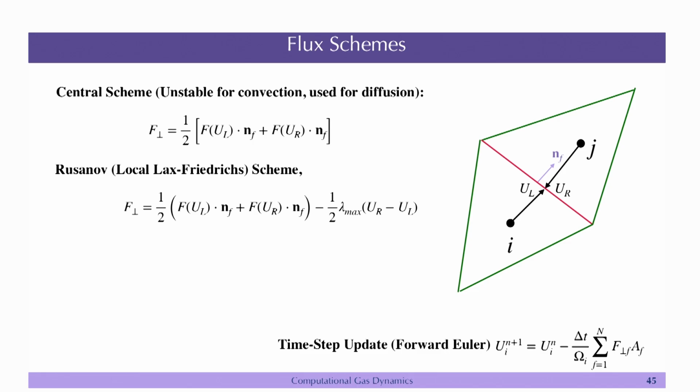For example, if you use an OpenFOAM kind of solver, you have basically rhoCentral form. They use some kind of modified central differencing scheme. There the time step required is very small; the CFL number has to go below 0.3 or 0.2.